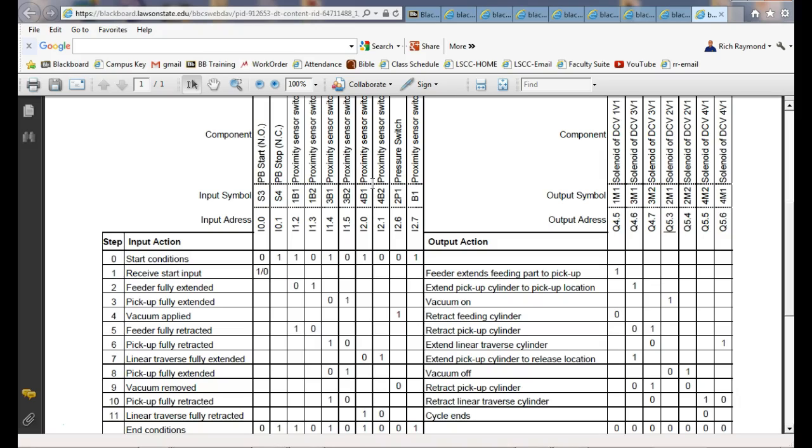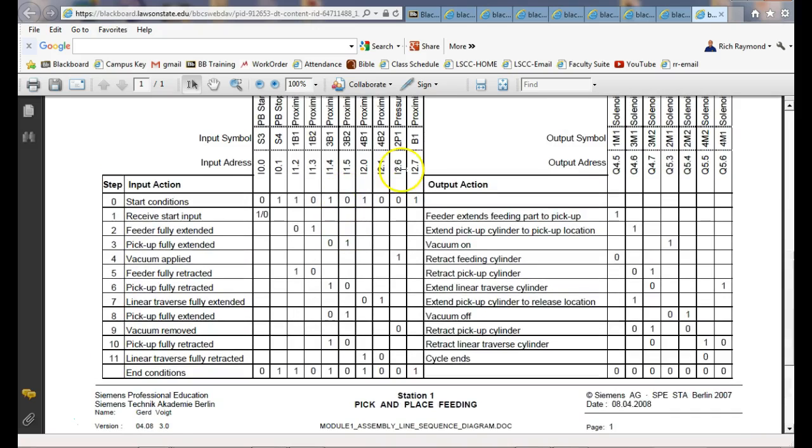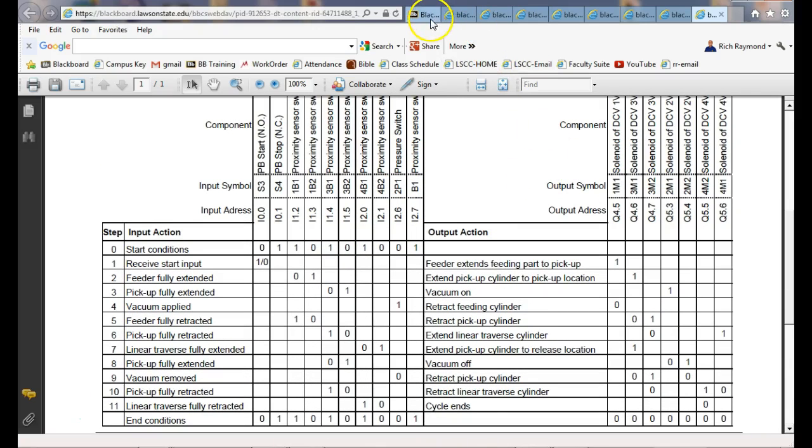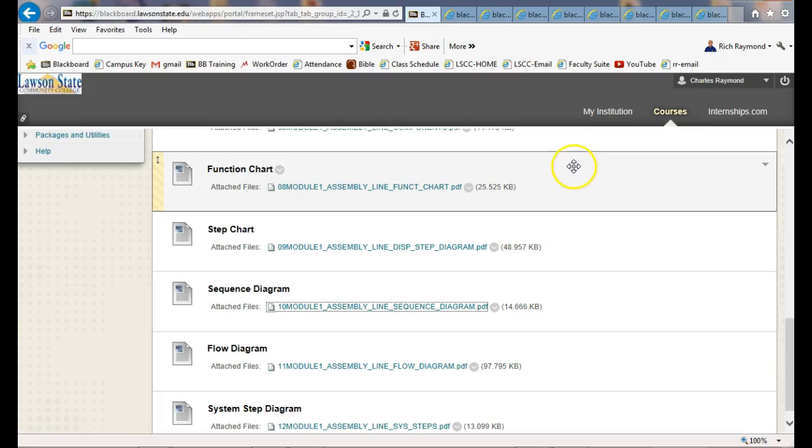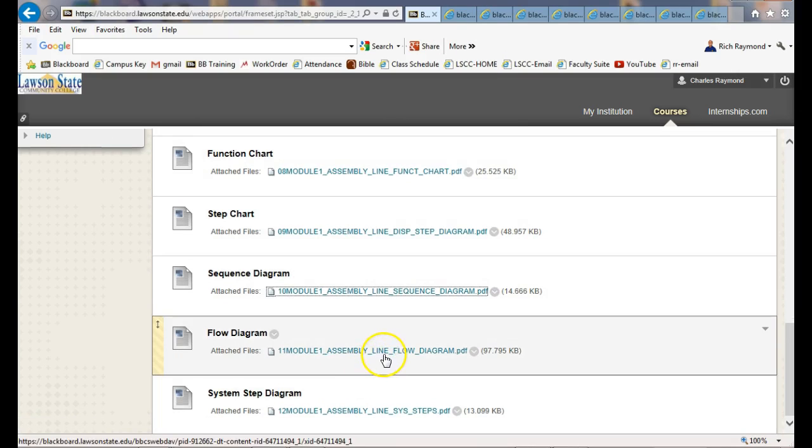It would be a good suggestion just to set up this chart. Get out there and watch it on the startup and see, okay, before you press start, let me go over there and look at these PLCs and document what's required to start. If you get that opportunity, you'd probably get an attaboy for that one, especially the first time it went down and you fix that in hardly no time at all.